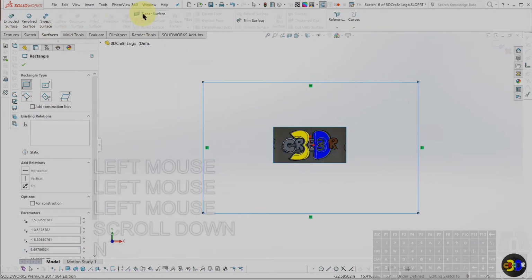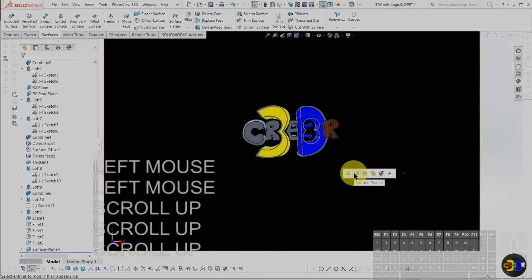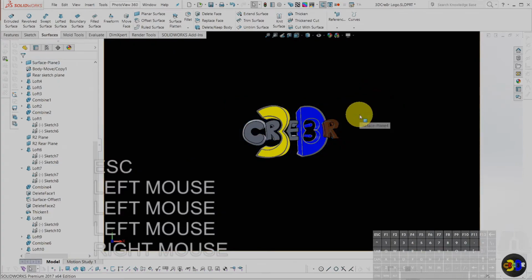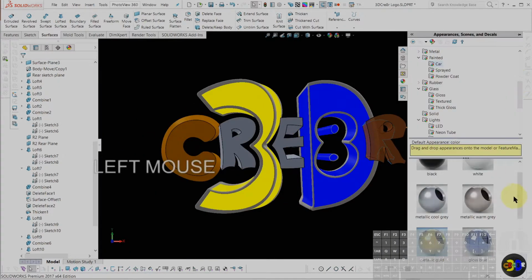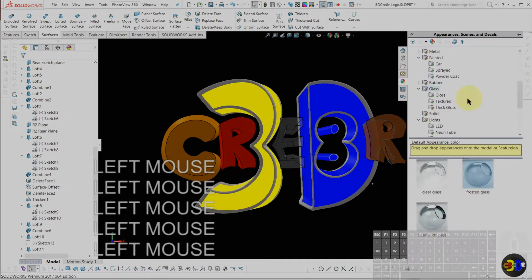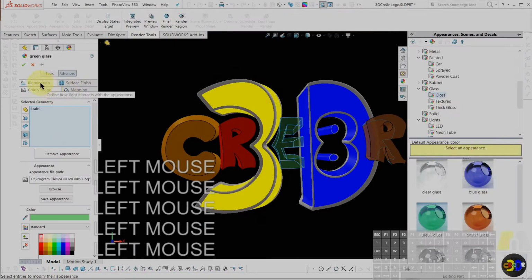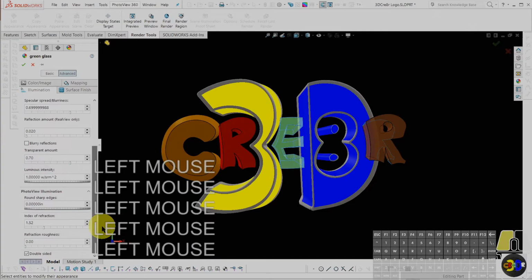I will increase it here. So right now it's 0.1. Let's say 0.25. Probably good. I can adjust it. Oh, I hit rebuild. Edit sketch. I was going to say I can adjust that later, but I suspect that once I trim this, it won't let me adjust the offset. I can confirm that. So I'm going to go spline.